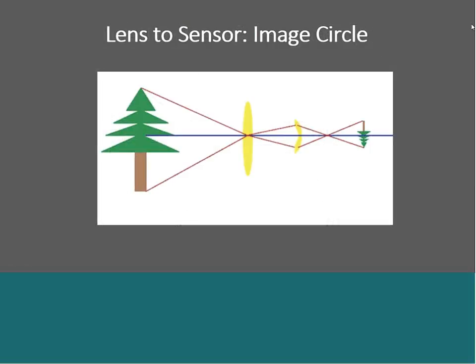So let's talk a little bit about the lens itself. You take the scene and send it through a lens, and then you put that onto some kind of digital sensor. Usually a lens consists of a series of stages of light transmissive material, and the photons from the scene are refracted in various ways to be focused onto the image sensor.